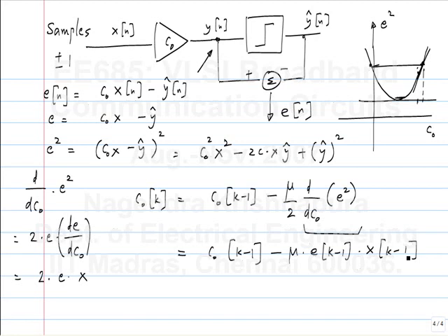No, firstly error is both positive and negative. So when you say minimize, it will go to minus infinity. Right? Absolute value? Yeah, I think it's harder to get an analytical expression in that case, that's all. But if you minimize e square, you are minimizing the absolute value also. And of course, the minimum mean square error gives you the best performance in presence of noise. We have not dealt with that here. Here there is no noise, but that's an aside.